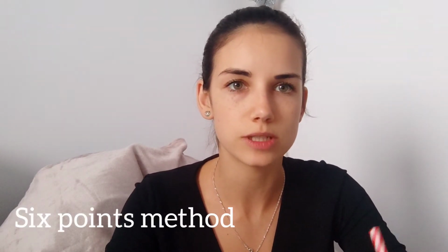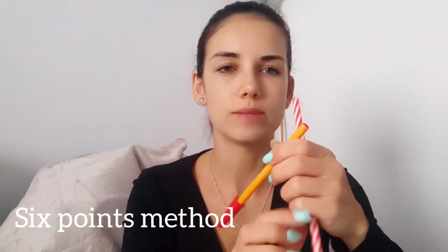If you want coordinates in a special way, where you choose where X, Y and Z are, you need to use the 6-point method. The first 3 points are the same as in the 3-point method, but for the rest you need to show the robot where X will be, where Y will be, and it will calculate Z, of course.